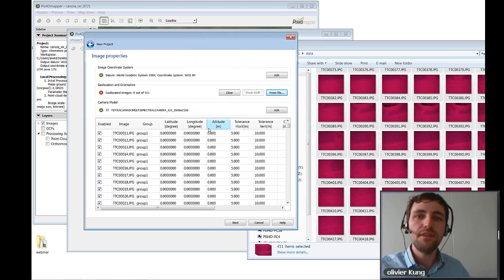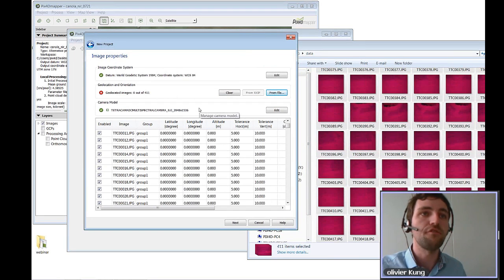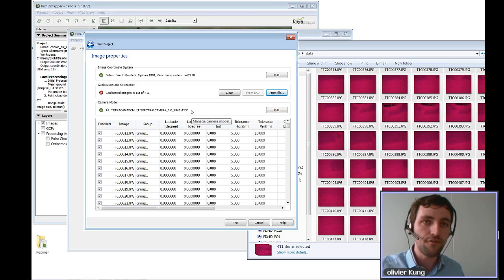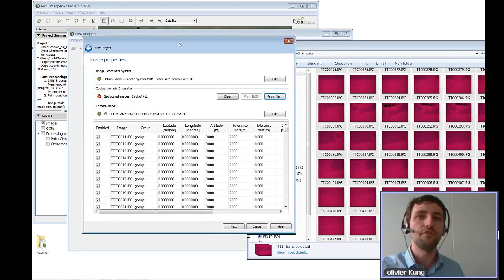It would indeed be an advantage to import the raw picture files, but there are way too many cameras which exist right now with different types of formats. So what we do is we let the camera manufacturers provide an export from RAW to TIFF, which is almost not destructive in terms of information, and Pix4D Mapper is able to read the full 16-bit TIFF information to process it correctly in the further tool chain.